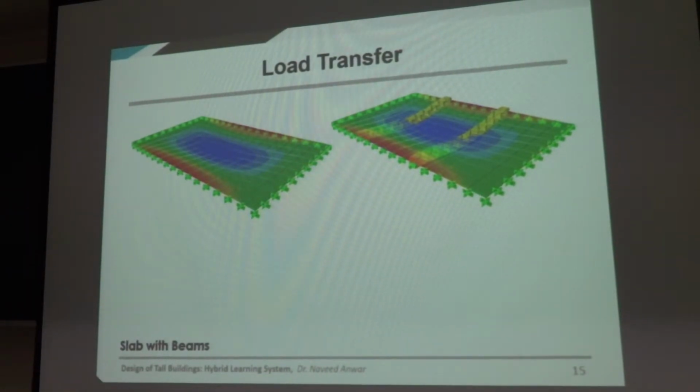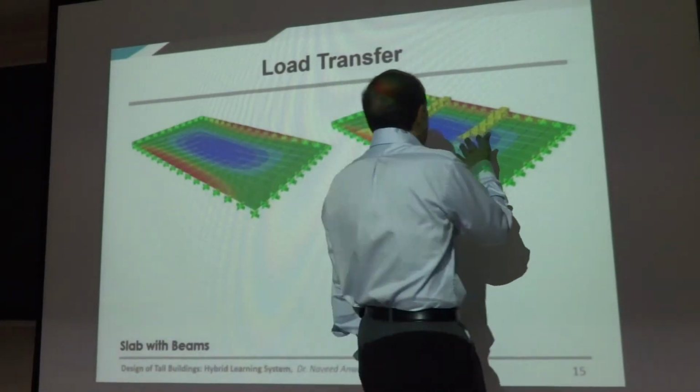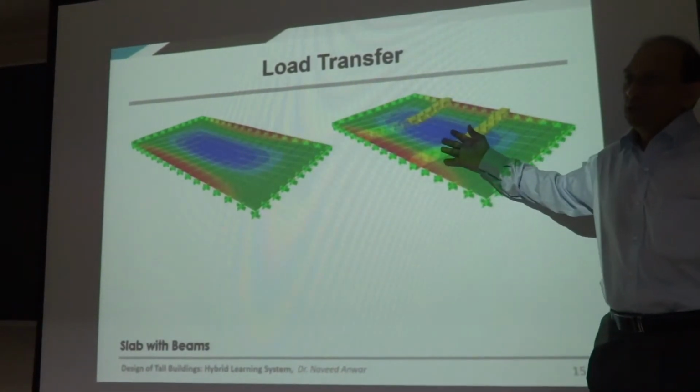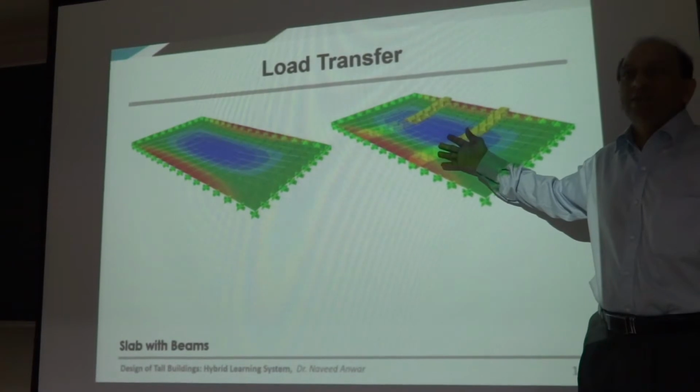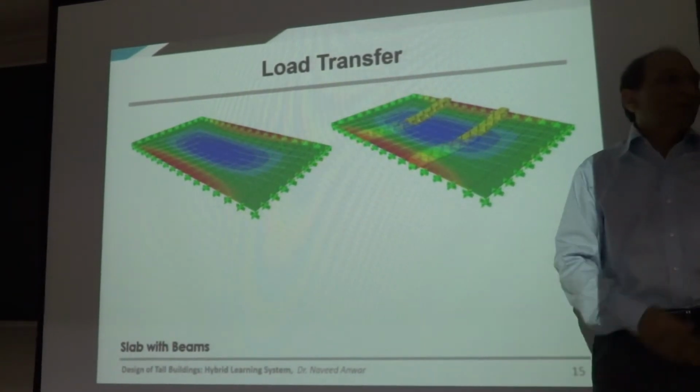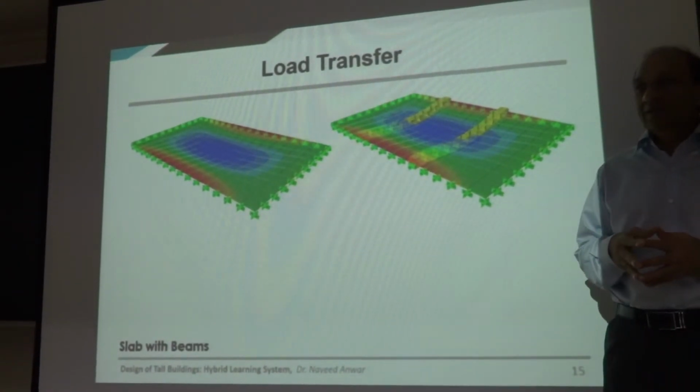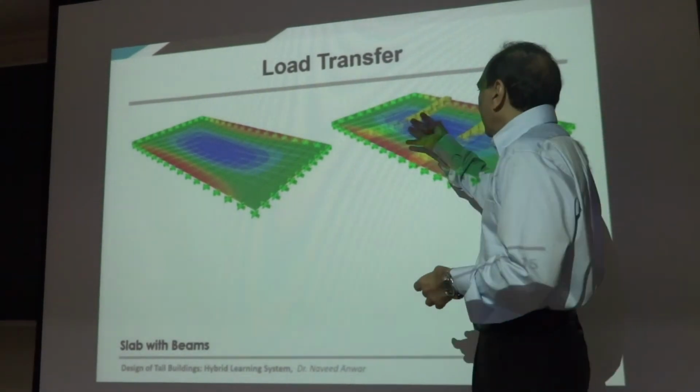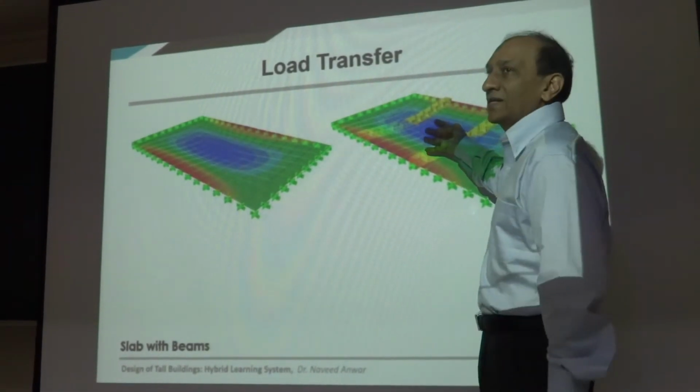And so if you try to design these beams based on a geometry base, you will kill them. You will transfer so much load to them which they cannot carry, and you will put a lot of reinforcement which is totally not going to work, and you will dangerously design this as 3 panels whereas it is acting as 1 panel.